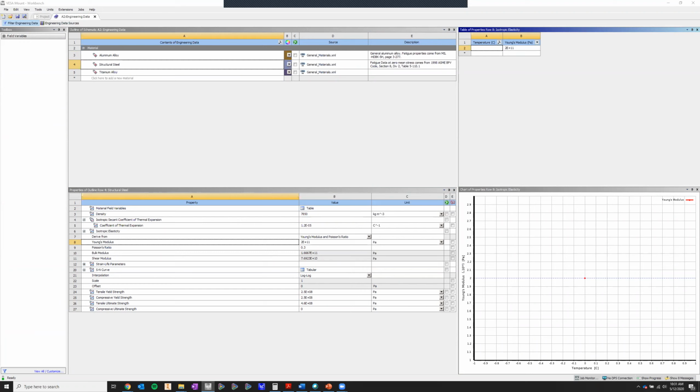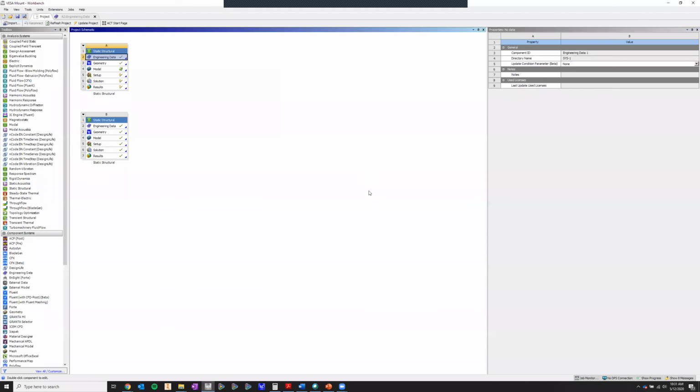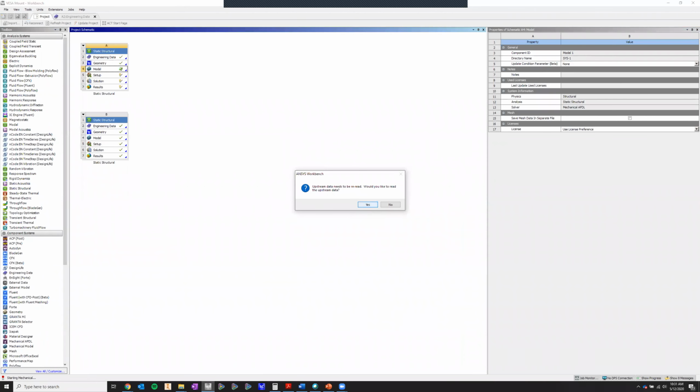What is the contact type used for the point mass that I applied? Let me reopen my model over here. So what Ansys does is it creates rigid points. Let me try to open this up and show you.